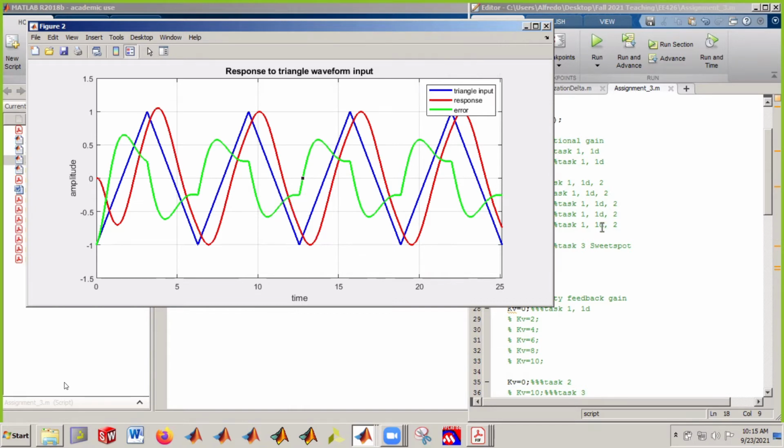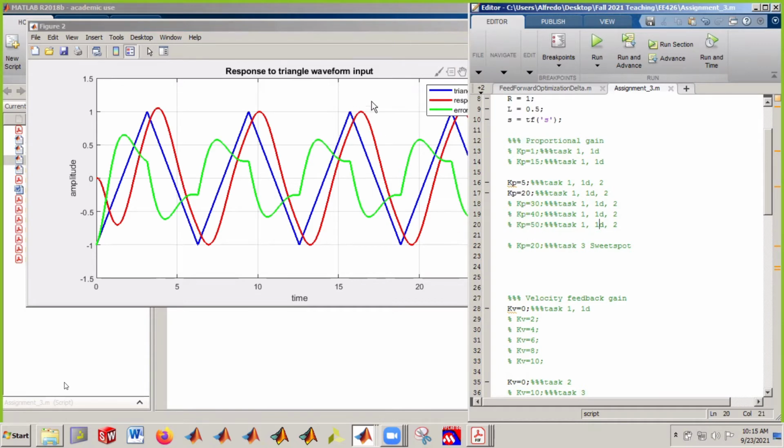So now why am I bringing this up? Because you will see the effect of the velocity feedback here. And you will see something very interesting happening in the other phase where this thing is actually getting closer and closer. So this is what I'm bringing up. In the transients or in the fast transitions of the input, you'll see the highest errors. Now, when the input is just steadily changing without fast transitions, this is where you see the motor position trying to get closer, ever closer to the desired position. And the error is the smallest here. Okay, so we have the highest error in fast transitions, and we have the smallest error in the steadily changing input, where there are no fast transitions.